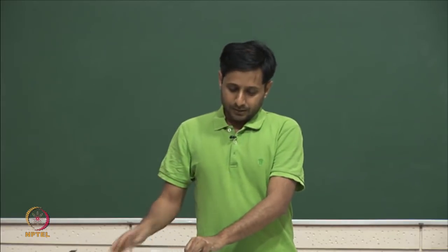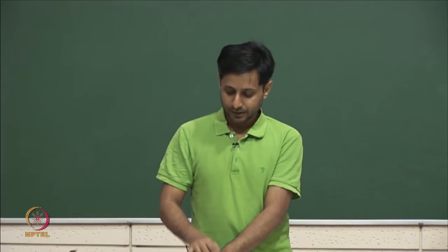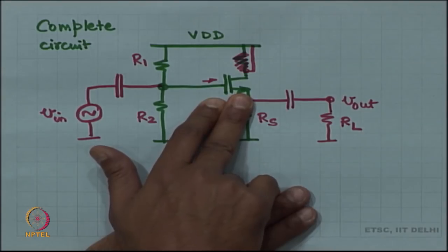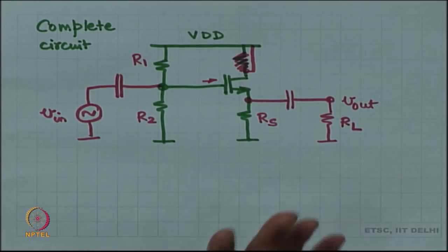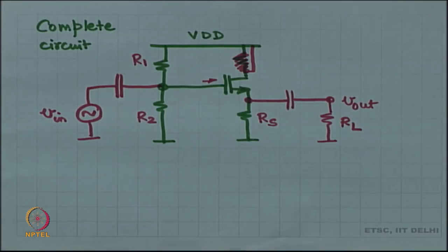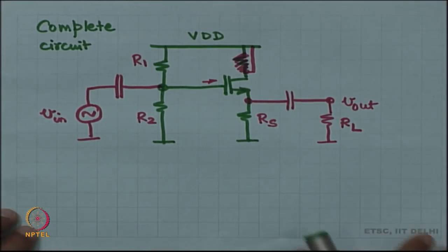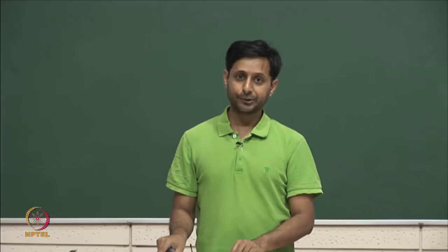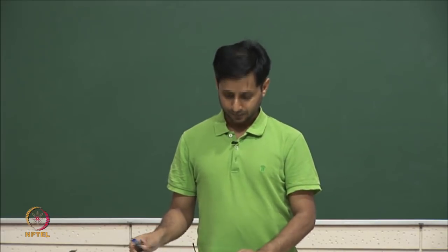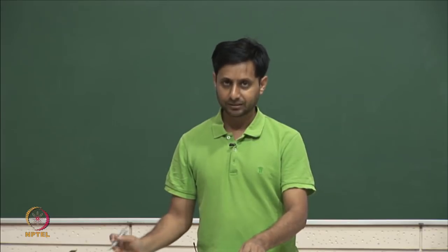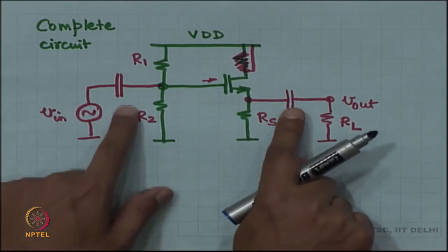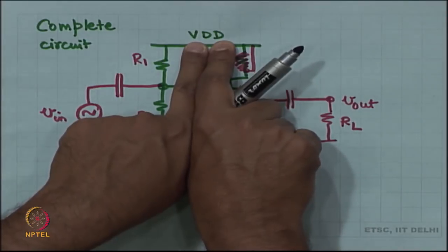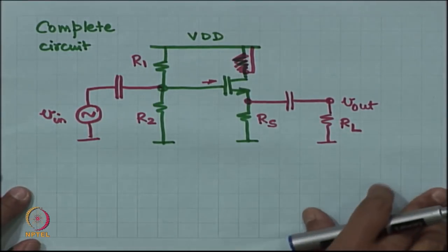Okay. So, my recommendation is, do not draw the small signal model of the MOSFET in the first go itself, right. Redraw once and then redraw a second time if needed. Right now we will need to do it because we do not know the steps, but later on you will find that you do not need to redraw it the second time. Okay. So, I am going to redraw this with what? What am I going to do? I am going to short circuit these capacitors and I am going to null the voltage source. That is the job that I am going to do.